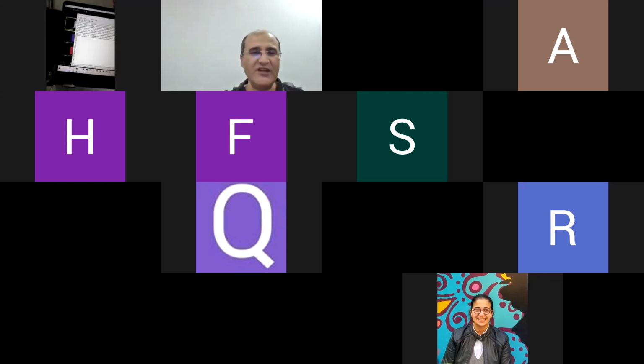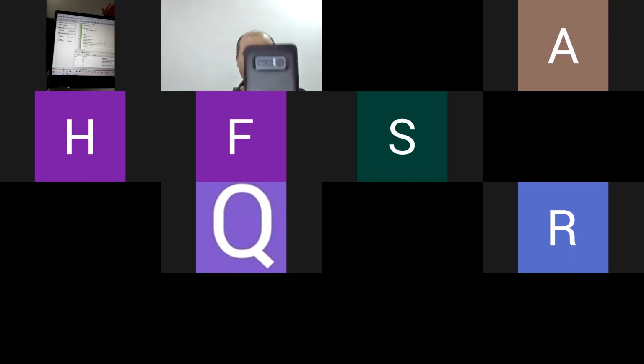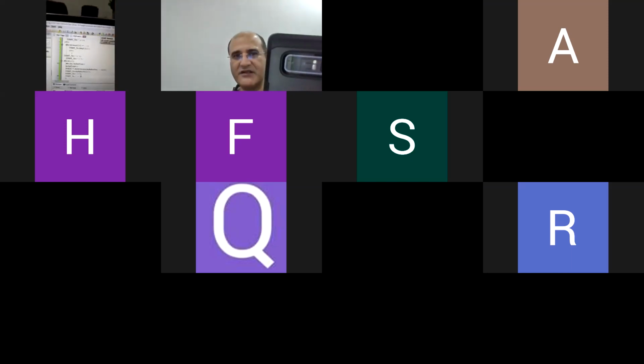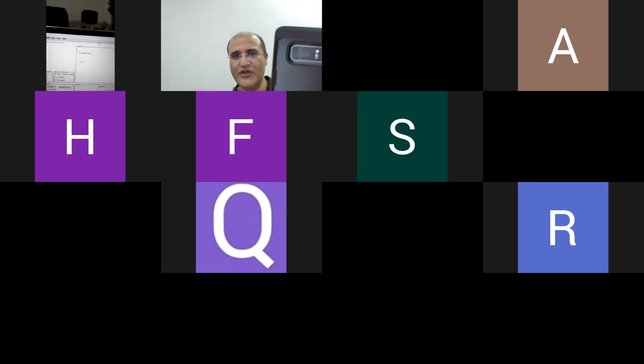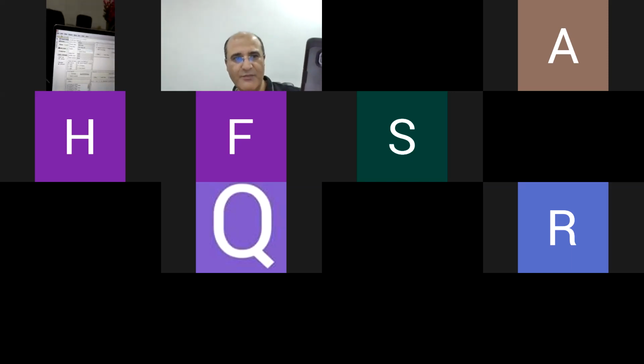What I'm doing here is using the hyper terminal, so you can use the hyper terminal. I'm gonna disconnect it now. Micro C has a terminal built in it. Here. You see it? This button. Push it. Select COM port. Set the baud rate. Stop bits. You see it, right? Stop bit. 8 bits. Buffer size. Okay. Then you do connect. Now we're connected. Now you can send here.